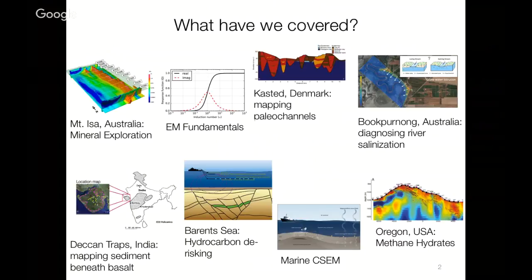But also in then combining that with drill hole measurements and getting a 3D geologic or hydrogeologic conductivity model. And then that allowed them to do some pumping tests so that you could decide, okay, if I'm pumping water out of here, or maybe I'm injecting it, then you can find out where the water is going, whether wells are connected, all of those things.